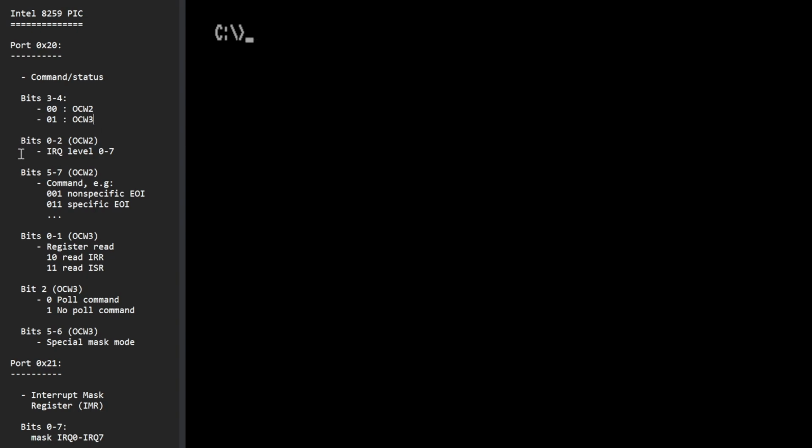So I've written out the description of what the bits mean if you're sending a control word 2, and below that I've written out what the bits mean if you're sending a control word 3. So let's start first of all with a control word 2. We won't actually need that in today's video, but we might as well cover it while we're here. Operation control word 2 can be used to send a bunch of different commands to the PIC, and I won't list them all, they're in the datasheet after all if you're interested. I just want to highlight a couple which are used more often, the end of interrupt commands.